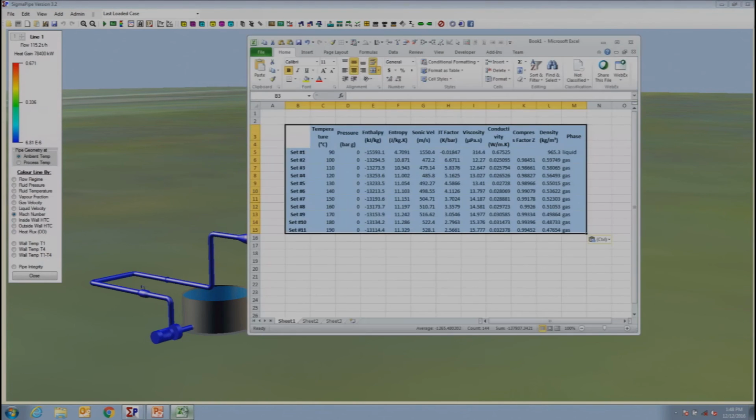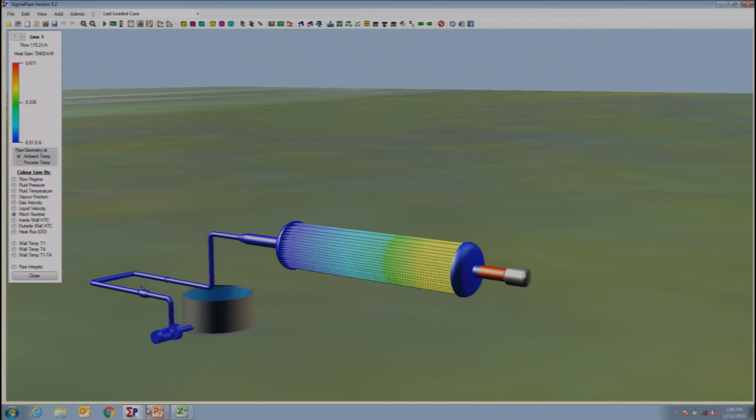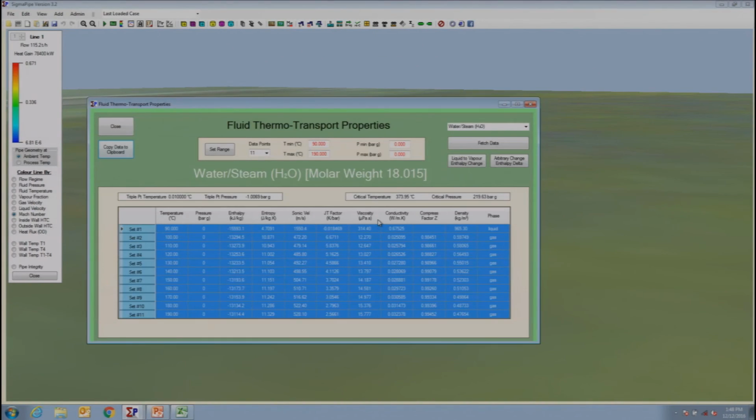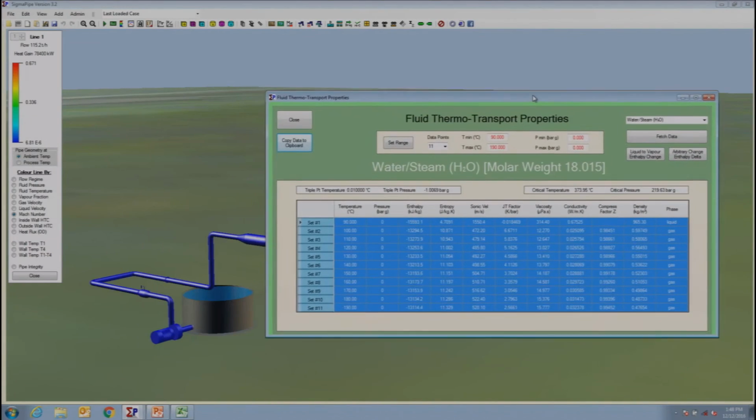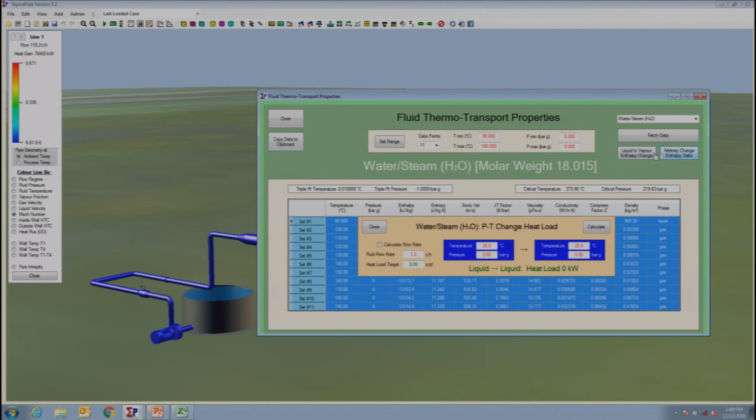The final thing I'll do here is demonstrate a sort of independent check on what this model is trying to tell us. We've got 115 tons an hour of water going through there, turning into steam. It's chewing up about 78 megawatts of energy. Let's just do a quick independent calculation. Does that make sense, that much water turning to steam under those conditions? There's a utility here that's very easy to use for that.